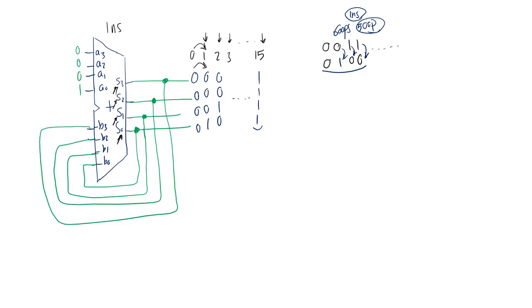So my counter is basically going to be outputting gibberish to me. It's not actually going to work, and not only do I not have any control over the timing of these transitions, the output is not reliable anymore. So how do I actually fix this? Well, the idea to fix this is to gate this feedback connection.